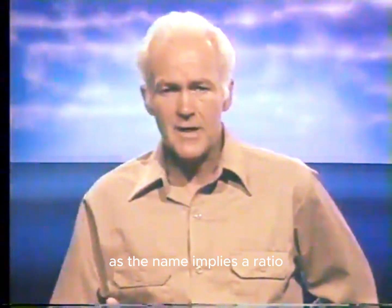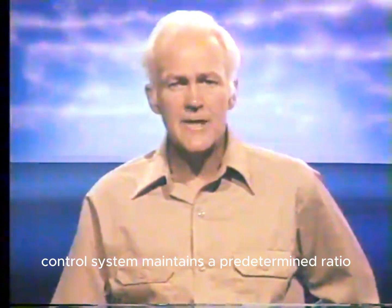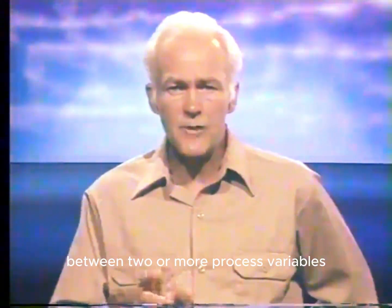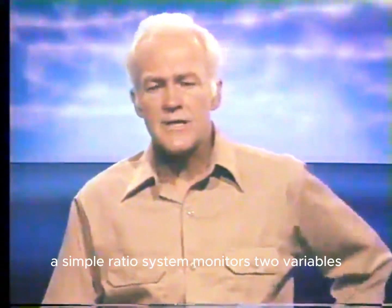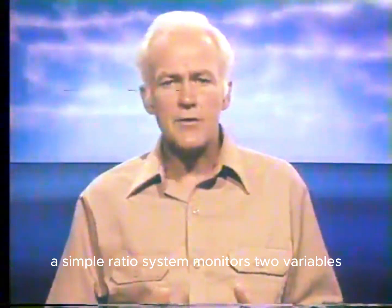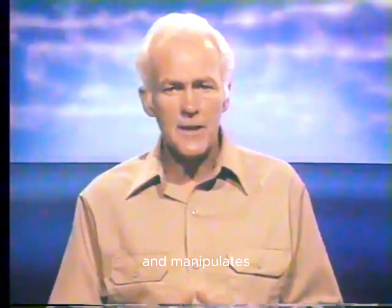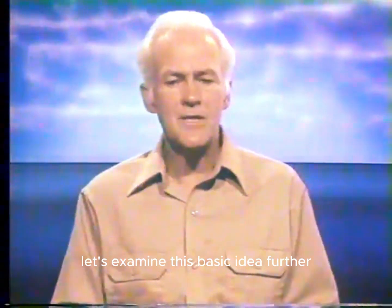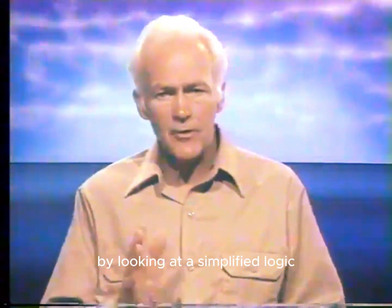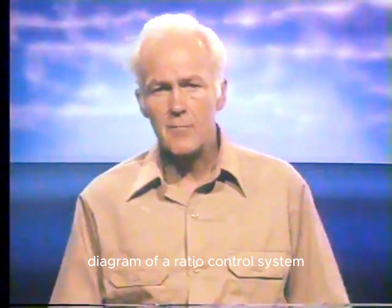As the name implies, a ratio control system maintains a predetermined ratio between two or more process variables. In general terms, a simple ratio system monitors two variables and manipulates one of the two to maintain the desired ratio. Let's examine this basic idea further by looking at a simplified logic diagram of a ratio control system.